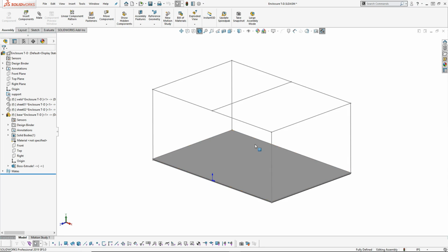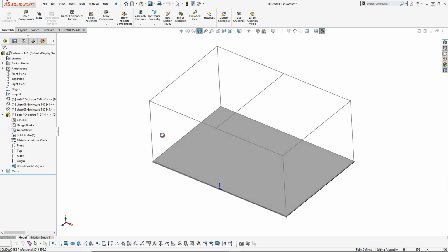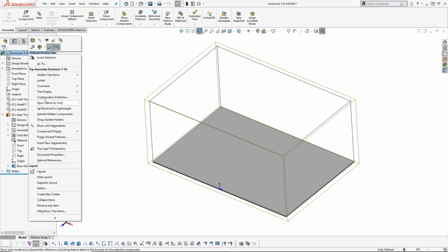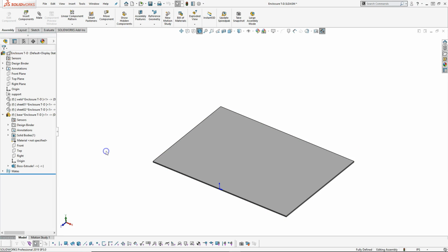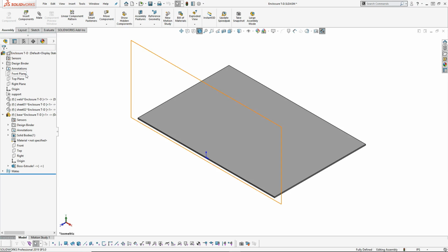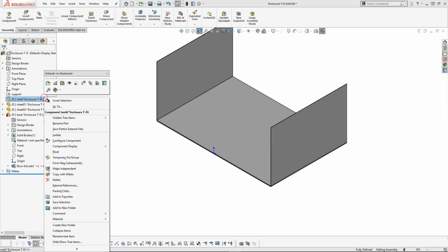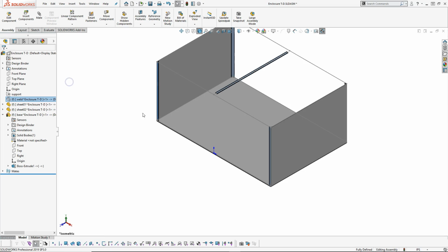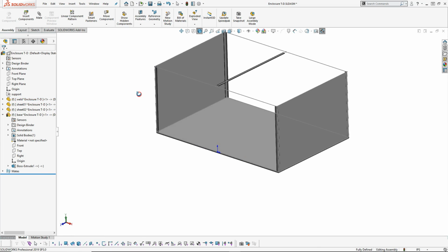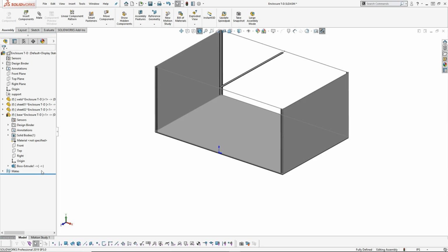So at that point, I'd go ahead and build in the rest of the holes, the geometry that I need for the pattern, and at the end, we hide the layout, hide the sketches, the support, and then let's see if we do Shift Tab and Shift Tab, and then on this one, since I don't have it expanded out, I'll just go ahead and do Show Components. Alright, so there's a lot left to build on this. I haven't seen that one before, so interesting.